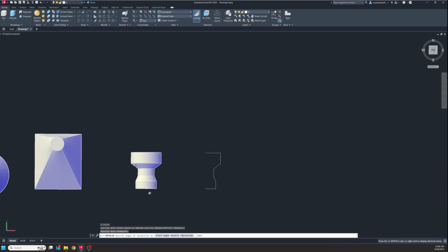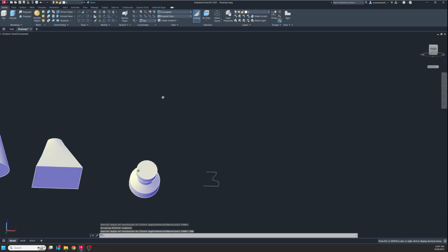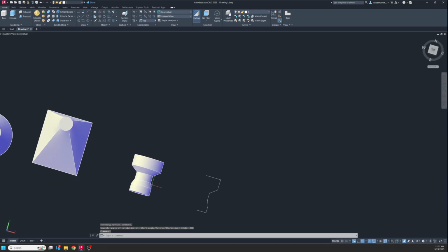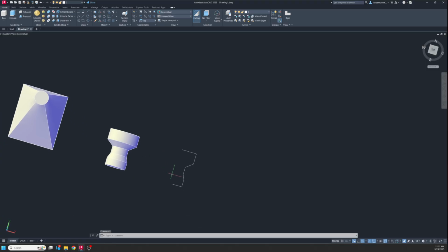And you can see that as I move that around, it's going to close or unclose it, or I can just say I want a 360-degree revolution, and now I have this solid that looks like that. Oh, I totally should have made a chess piece. Opportunity missed. Anyway, this is probably the easiest way to create a circular object that has detail in it, by creating the profile of that detail and then revolving it around a point.